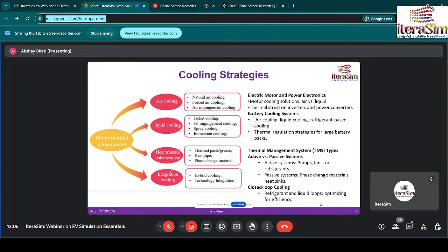And the mechanism is conjugate heat transfer, conduction and convection. Conduction in the electronics or any material part, and convection in the liquid. And where is the application? It is mostly used in data center cooling, increasingly used to cool servers and equipment, improving energy efficiency and space utilization. And if we talk about winding cooling of the electric motor, it isn't used in that segment.